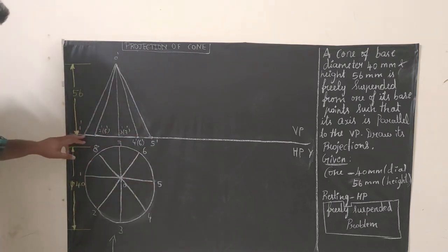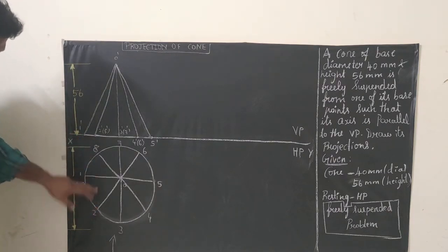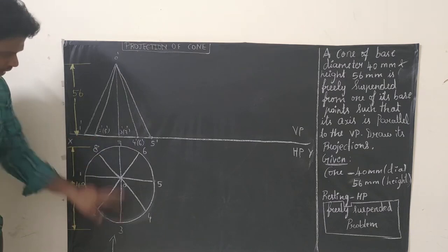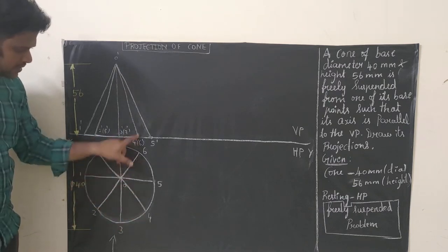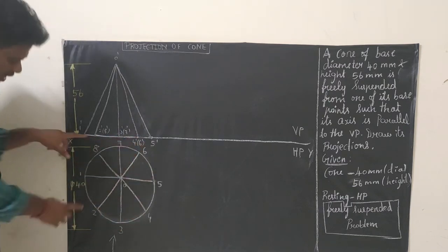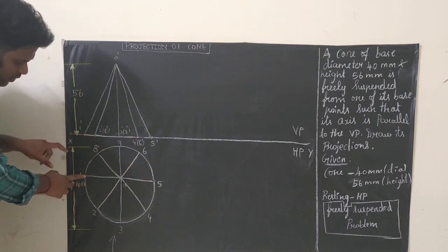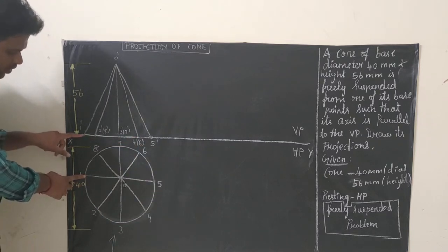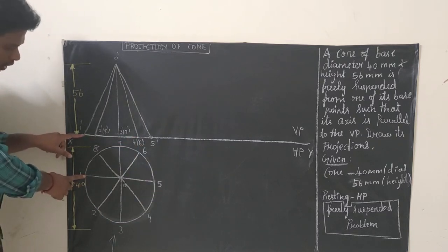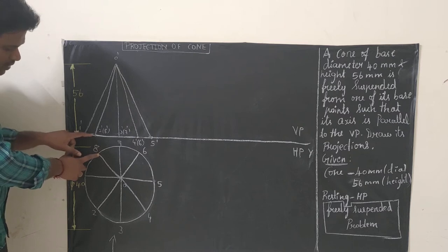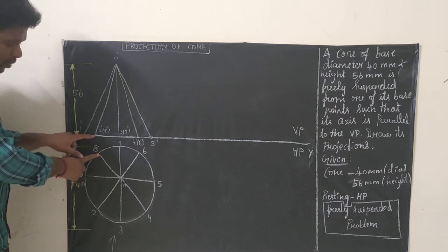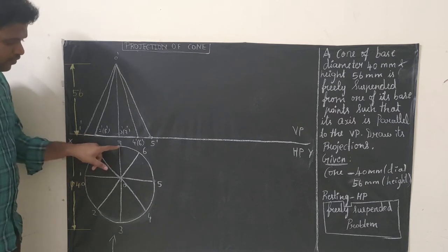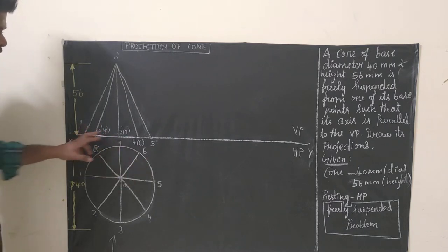Okay, so project the points so that we can get 1 here, and try to project 2 and 8 here, 3 and 7 here, 4 and 6 here, 5 here. Keep your scale, so wherever you are having 1, the same distance vertically at 90 degrees you have to get at the point. Wherever you are having 8, the same vertical distance you have to get the point 8. Same way for 7, 6, 5. Now we have plotted the points.